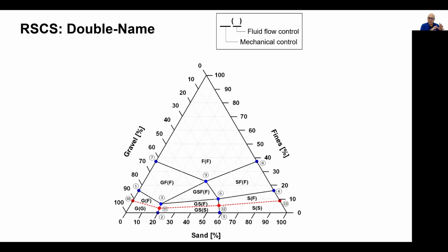Once you introduce the values that we have described before, it uses mass fraction equations that we presented earlier to identify all these transition points with Emax and Emin, and with the void ratio of the fines at 10 kilopascals and at 1 megapascals. Notice that there are blue boundaries and there is a red boundary. We have superimposed the 2 here. So for mechanical purposes, fines control in this upper part and then in this transition part.